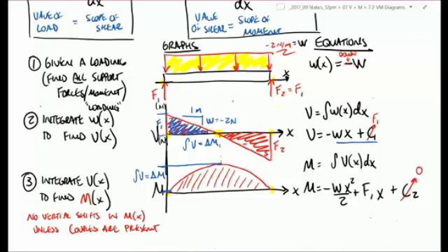The way that you do this to find the maximum moment, if you realize that it was at a maxima, is that you would set this shear value here equal to 0, right, and solve for where is the location of that maximum, and then you substitute that x value into your moment equation and say, all right, what's my moment at that location of x? Okay, so that's the equation-based technique.